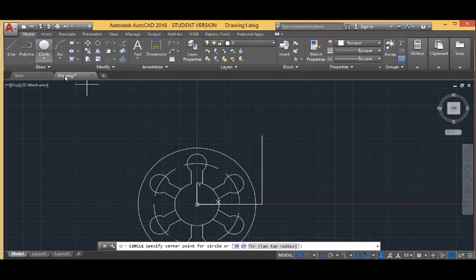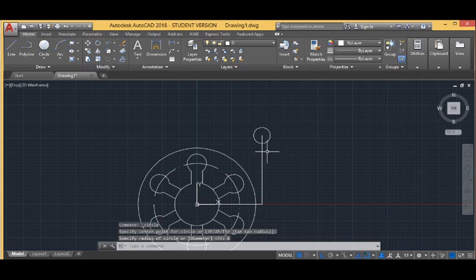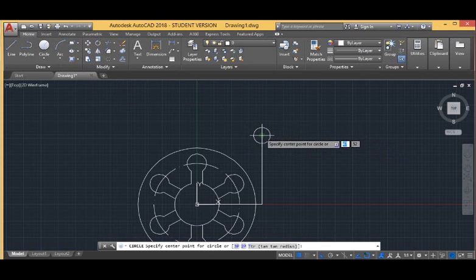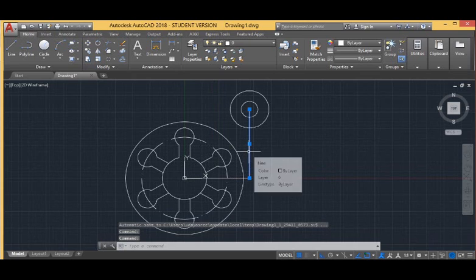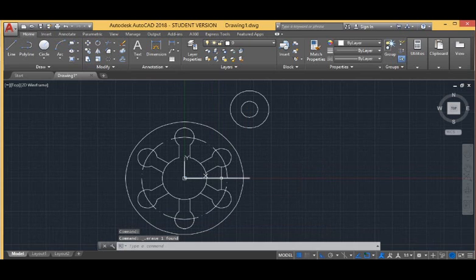So I'll pick the circle option. Here I'll make two concentric circles, one of radius 14 and one of diameter 12. So first diameter 12, it means radius 6, and the next one is the radius of 14. Okay, I have made two circles. Now I'm removing these reference lines. Now I'll make a mirror of all these things.